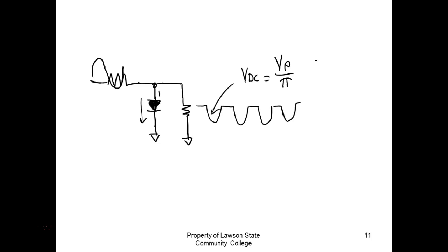Well, if the power source is DC, then if you reverse bias it, you get the full voltage. If you forward bias it, then you get 7/10 of a volt. So if I came over here and did this, I took away my DC and I put it like that, would that be forward bias or would it be reverse bias? Okay, it's forward bias.